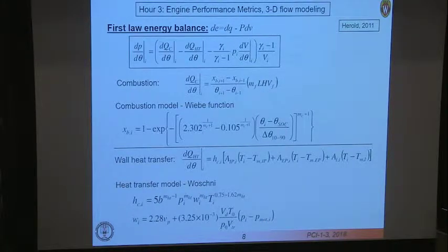So somehow it's related to that; it gives you a feel for how much combustion has taken place. That influences this W. Also, the piston velocity appears here. So that goes into determining the convective heat transfer coefficient, which then gives you this term. So we can then calculate the pressure change with crank angle using our first law analysis in response to the combustion and the heat losses.